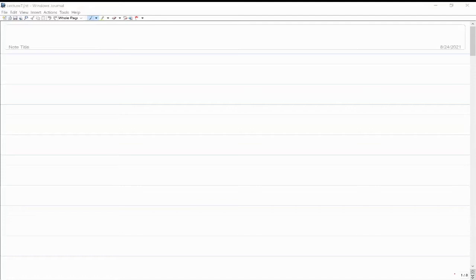So on the boundaries there would be a transverse force that we denote by capital Vn, and there would be a moment on the boundary. The moment would be about the tangent to the boundary, so that we denote as Mn. So these are the two contributions from the boundary tractions and moments.